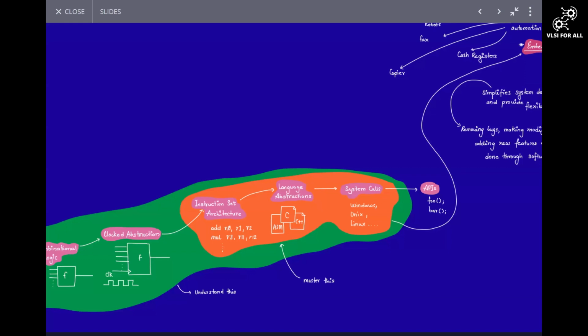There is a simple algorithm called the round robin algorithm, wherein each task is assigned some specific time duration. Let's say 1 second. Every task will run for 1 second and then switch to the next task. It will run for 1 second, switch to the next task. It simply goes in a circle. Round robin. There are other mechanisms as well based on priority. So task switching is the first concept that you need to learn.